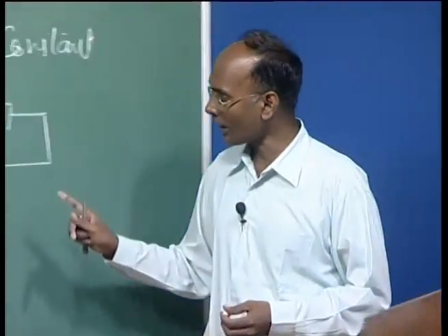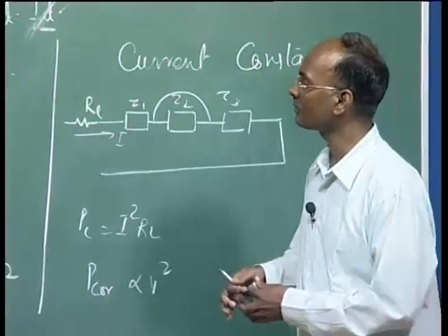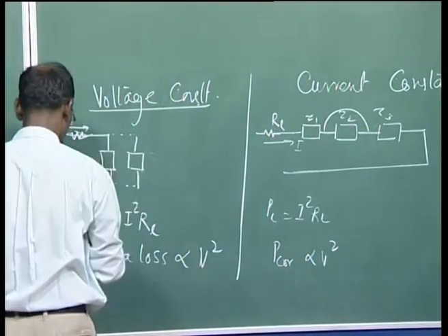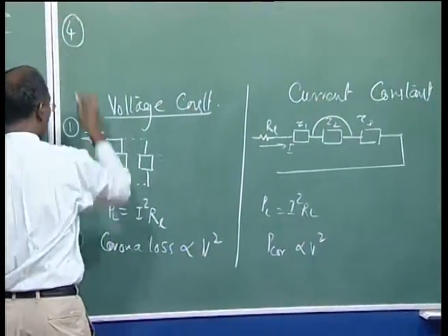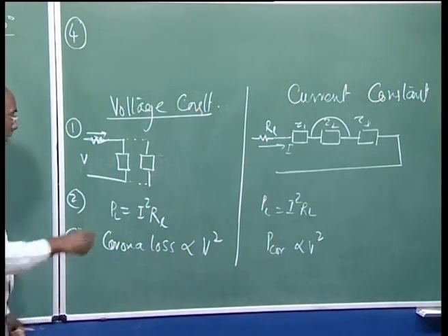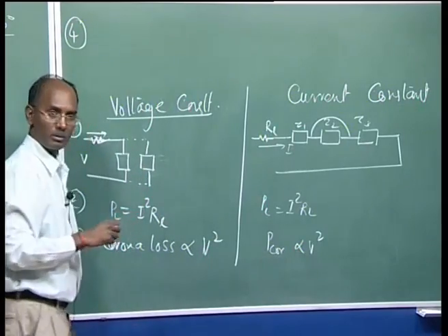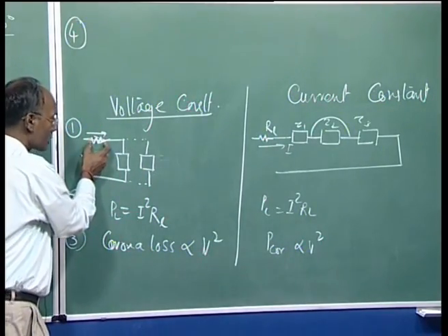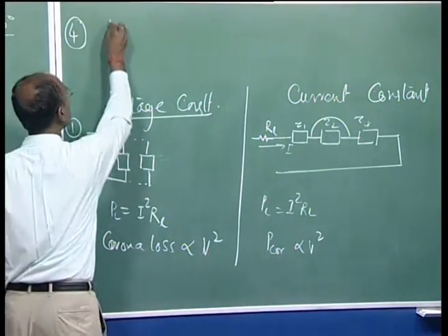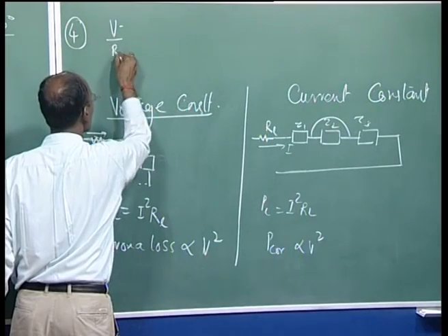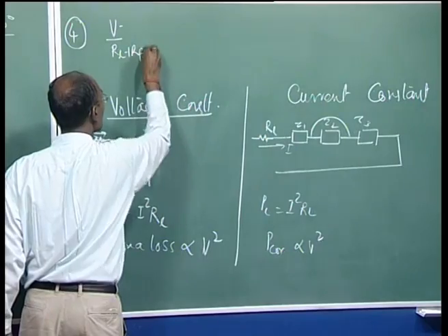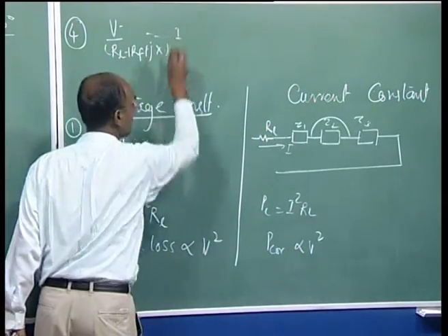Means why we are operating here with constant current, that is related to your constant current here, and I can say your fourth option. You see, if there is any fault in the system here, what happens, you have the circuit breaker, and not only resistance, you have the reactance of the line as well, and therefore here the voltage divided by this R, whatever you can say, this line plus your fault resistance plus, you can say, jX, whatever, this is the current which is coming.